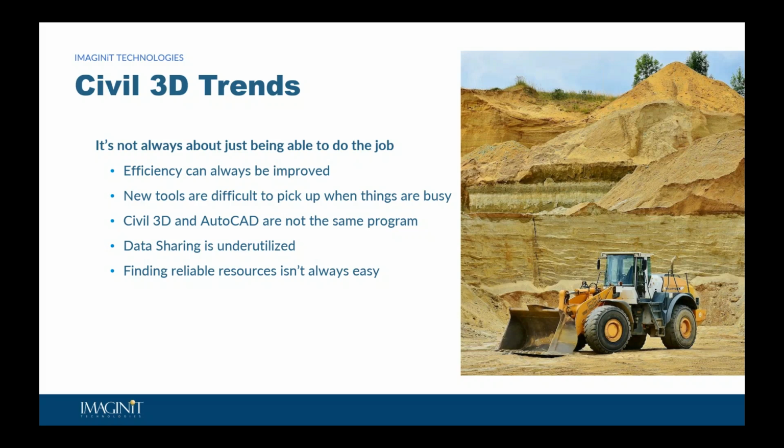We also find out that data sharing is very, very underutilized. We hear a lot about files that are all contained within one particular drawing file versus being split up with data shortcuts or even external references in some cases. Or we find out that a lot of things are being copied from one file to another rather than shared. So although they are splitting files up across multiple drawings, they're actually creating copies of things instead of linking them all back into one.